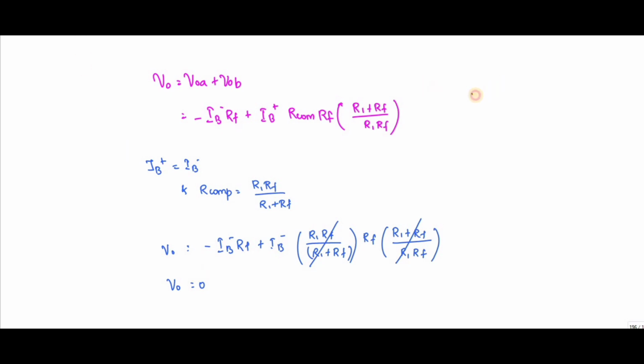So usually you can see the IB value is nothing but 500 nanoampere. Okay. It is in the range of 500 nanoampere, and it may go up to microampere. Okay. So if I use a precision opamp, these values will go as low as femtoamps.